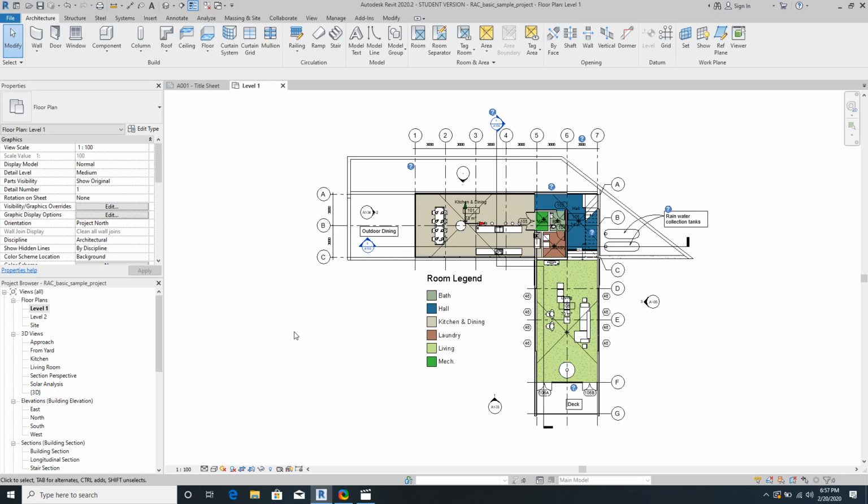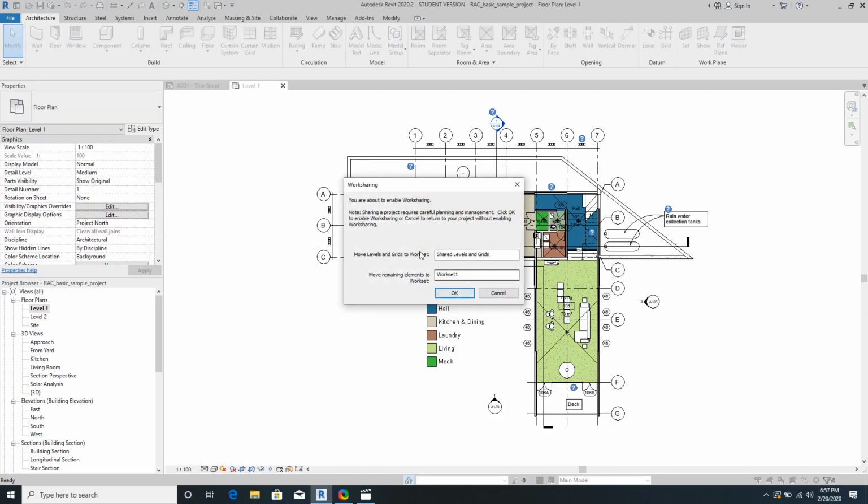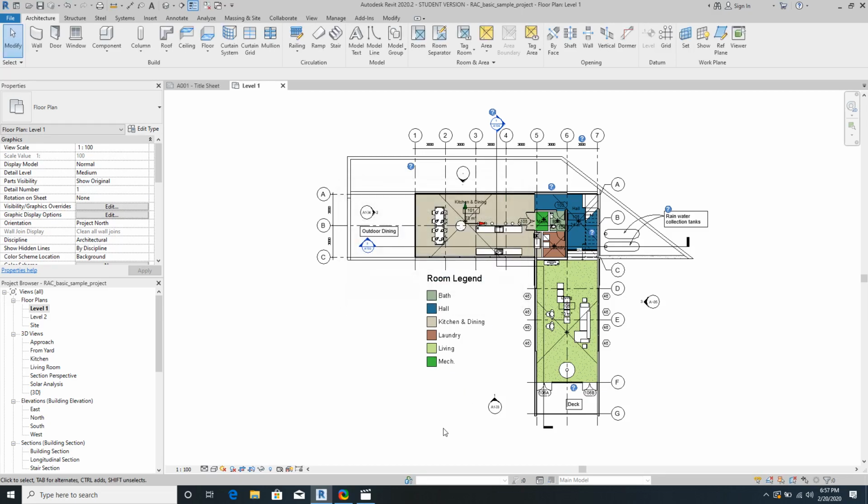Now in the middle, we have some other icons, like the worksets icon. So if you were coordinating with different disciplines, you would click this icon and it would bring up the different worksets available to you. Now over here, on the far right, we have the selection toggles. And those just control what classification of elements is currently selectable. So there are certain groups of elements that we can turn off their selectability, and that's going to be indicated by whether those icons have a little red X on them or not.